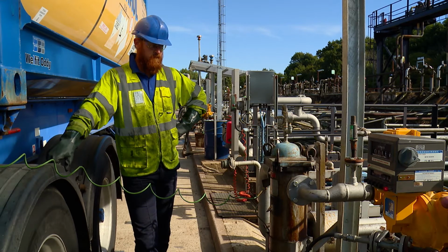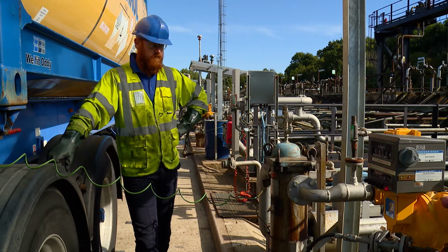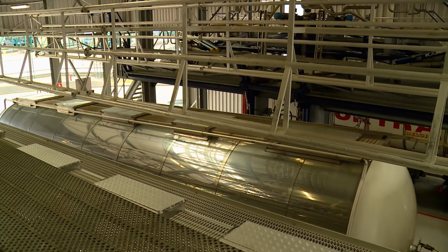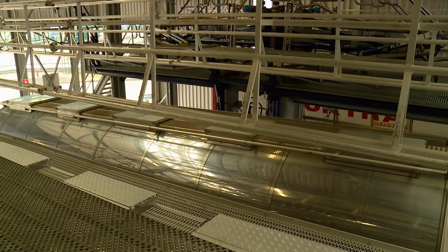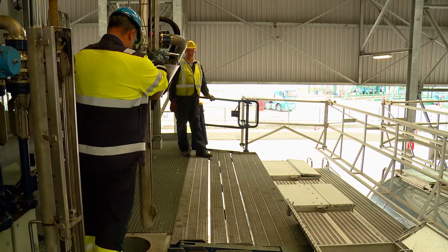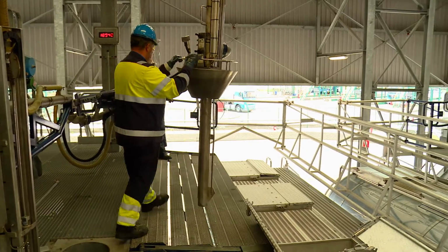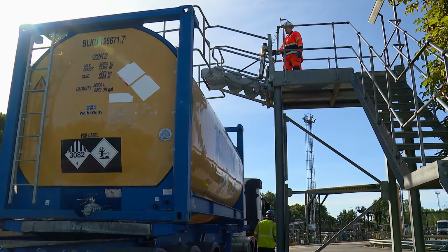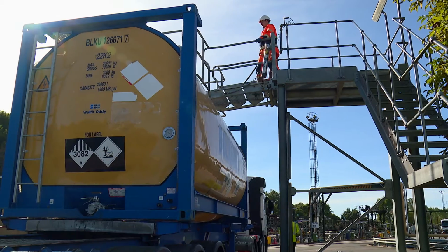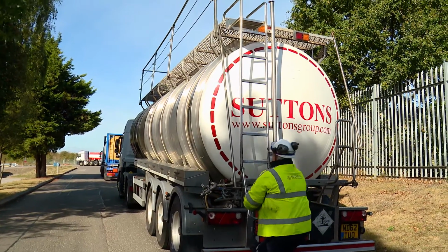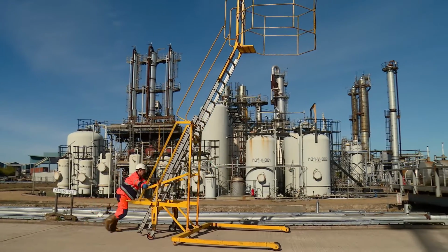Ideally, solvents should be bottom-loaded via a meter. However, if top loading is unavoidable, then splash filling must not occur. In consideration of working at height hierarchy, if access to the top of the vehicle is required, then a safe working gantry must be used if available. Alternatively, a safe system of work must be in place, which may include vehicle handrails, a fall arrest system, or purpose-designed enclosed portable gantry.